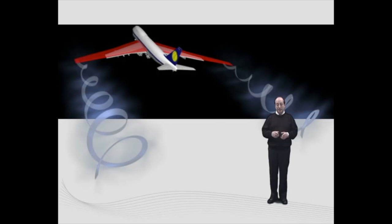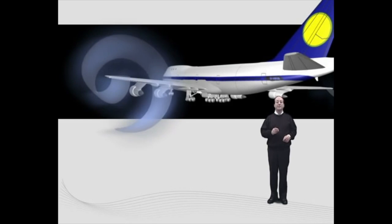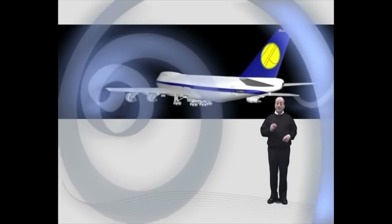The intensity of these vortices is higher for low aspect ratio wings and for high lift coefficient. The vortex wake strongly interacts with the lift distribution along the wing because it influences the so-called downwash, which is the mass of the air that the wing pushes downward. For these reasons, also the induced drag is influenced by the vortex wake.